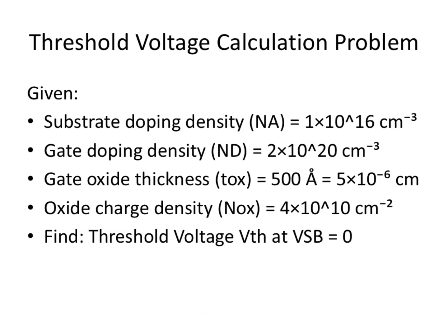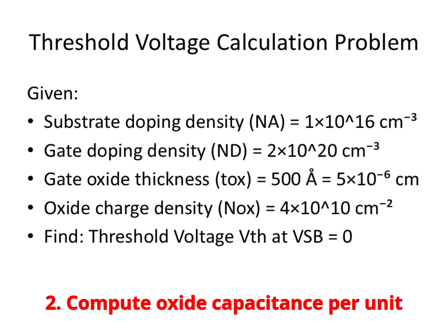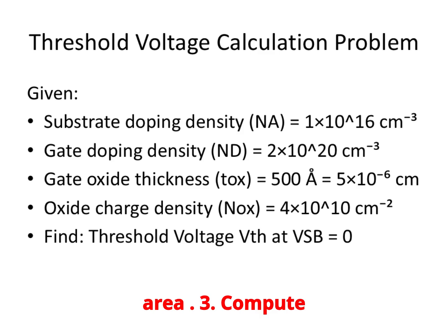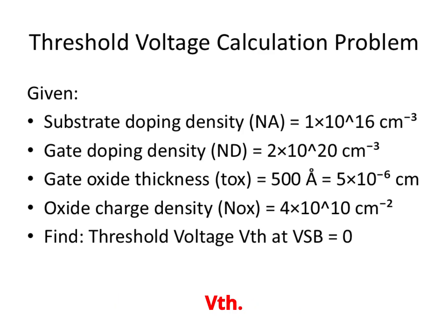Our steps will be: 1. Compute Fermi potential, φF. 2. Compute oxide capacitance per unit area, Cox. 3. Compute depletion charge, Q_dep. 4. Compute flatband voltage, VFB. 5. Combine terms to get final Vth.